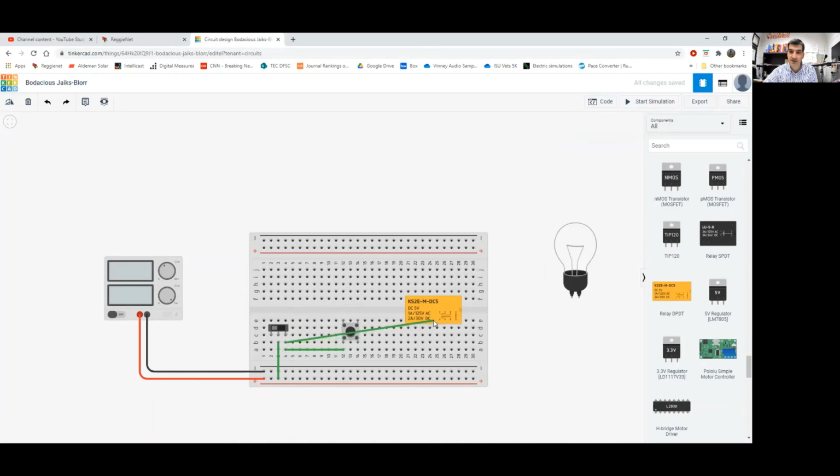What's the common in this relay? Well, if you look on page, I think it's 41, you'll see that the common for all the normally closed and normally open contacts on this side of the relay is this one in the middle, terminal 13. So I need to connect to one of these right here. So I'll go right there.